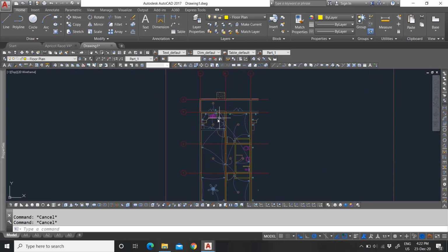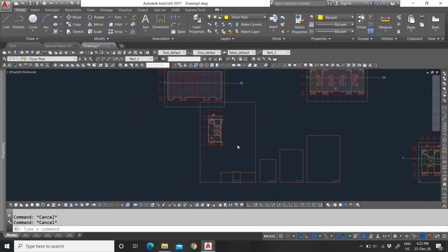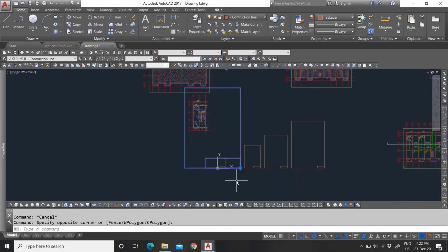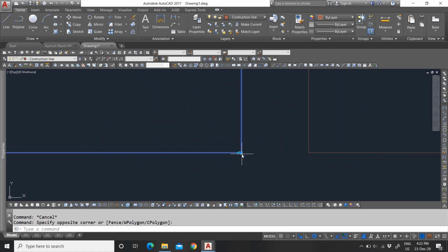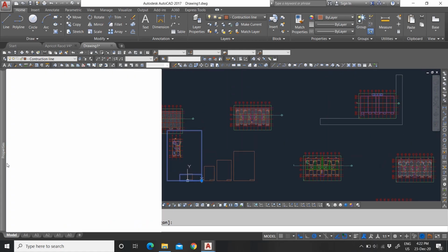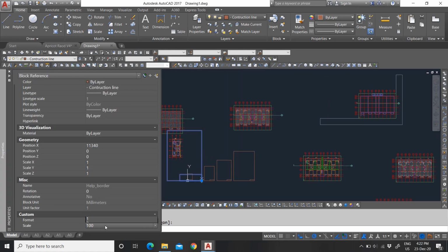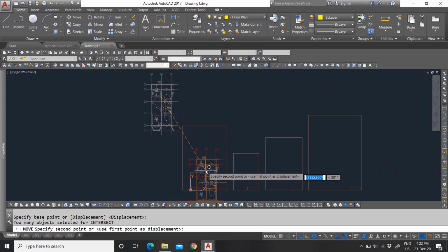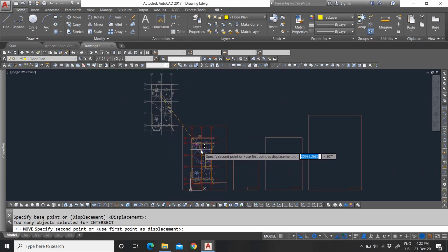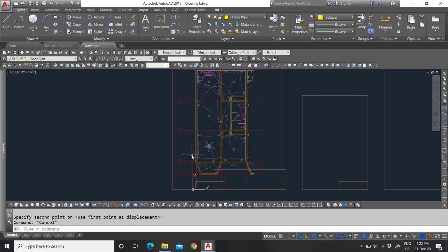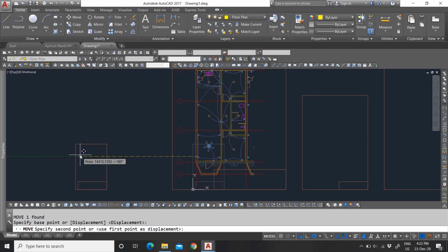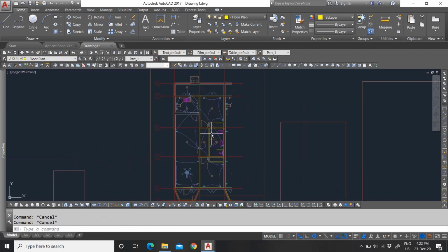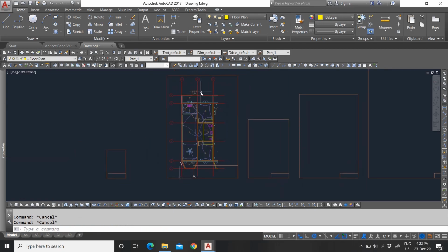So for this example, a very small example actually, I will use the A3 paper, but then not 1 on 100 because the drawing is not that big. Let us choose 1 on 50 to start out. Okay, so right here. And this one is my A4 paper, but I won't be using this one because my A3 paper is enough right now.